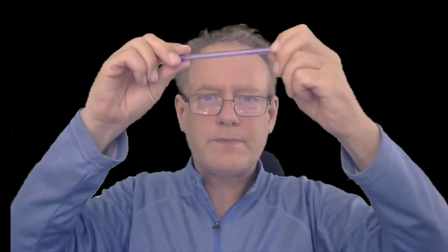I think we're getting down to how we generate it. So there's this conductor and it moves through a magnetic field this way. When that happens, EMF, electromotive force, pushes the electrons this way, or at least it will push them this way if there's a closed loop. If there's no closed loop, there's still the pressure, or the voltage, trying to push them. That energy is still trying to push the electrons this way. If I move that same conductor through the magnetic field, maybe I'll do it kind of like this.